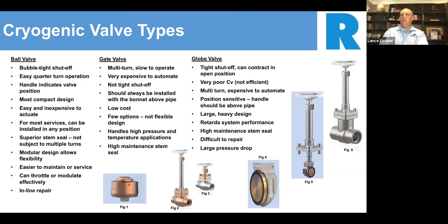You want that extension in there for safety from the packing, and also safety possibly from your users standpoint. The valve will start to ice up. That liquid cryo will make its way through that heat transfer tube and make its way to the top of the valve. So if you have an application where you're turning it on and off on a regular basis, I highly recommend you go with that extended stem valve versus a short stem valve.